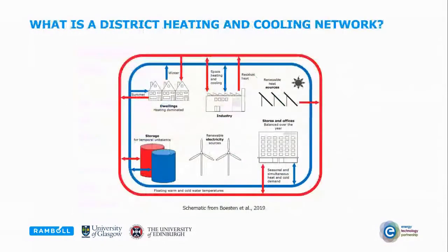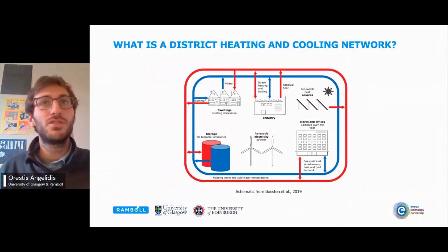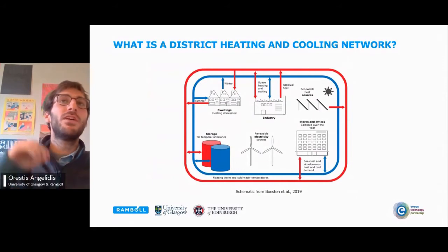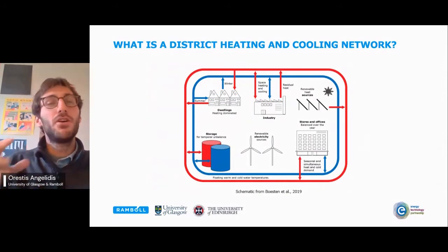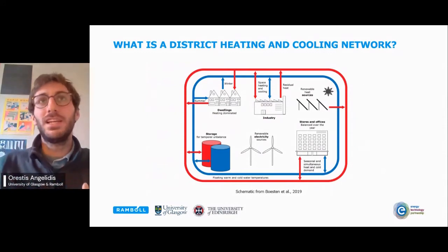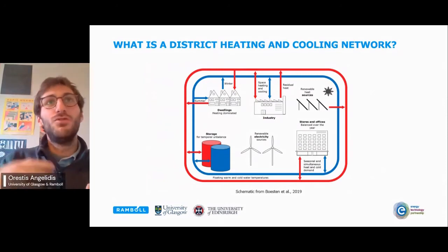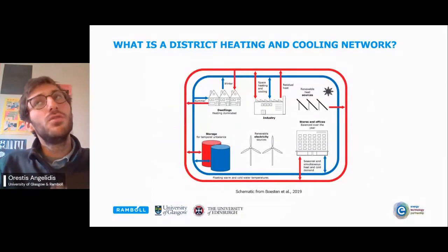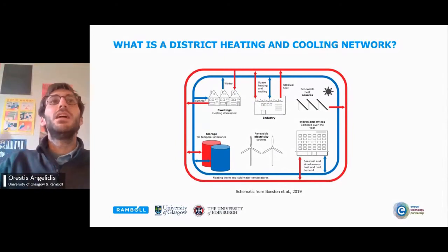So what if we were to take this a step further? And this is the idea that I want to discuss more today: the concept of district heating and cooling. So essentially we have one network of pipes for both, not 2 sets of pipes. And the concept here is that we can make use of the fact that somebody's heating is somebody else's cooling dump. So if somebody needs to cool down their data center or their tube station, we can use that heat, re-put it in the same network, and use it further down the line in dwellings.